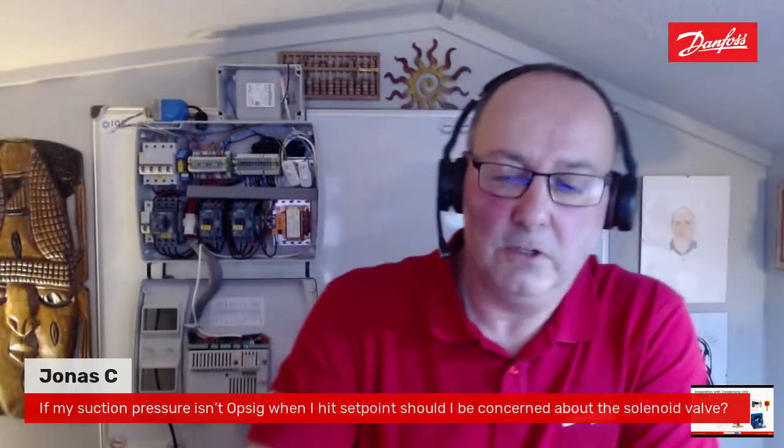Another strange one, Jonas, is make sure you've got the right voltage coil on the valve. I know that's more about opening than closing, but it is just worth mentioning that, if you've got 240, make sure it's a 240 volt coil, 110, etc., or 24 volt. Just make sure it's the right one. So hopefully that answers that one, Jonas.